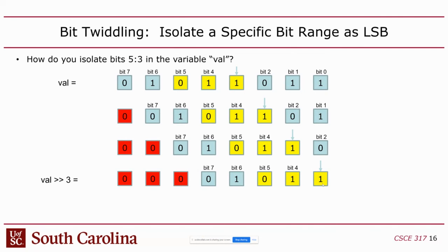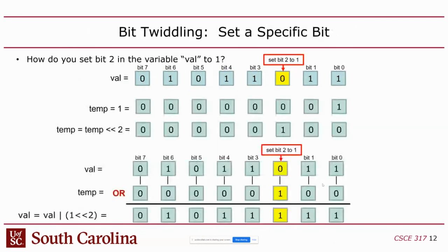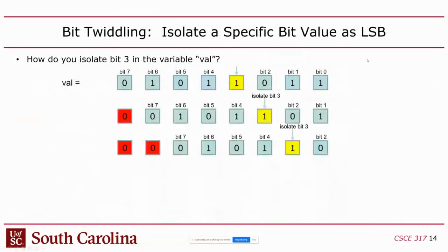So we'll shift it 3 bits to the right, which basically means that if you're looking at something like this in a user guide, this says 5:3. So when we do the shift, we're using the right value, the 3. So we're going to shift this by 3 bits to the right.